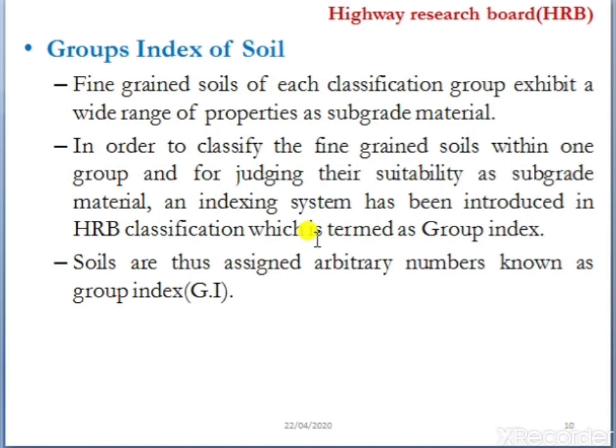So to know the different properties of that fine grained soil as a subgrade material, we assign a number to such soils, and that is called the group index of the soil. In order to classify the fine grained soils within one group and to judge their suitability as subgrade materials, an indexing system has been introduced in the HRB classification, which is termed the group index.